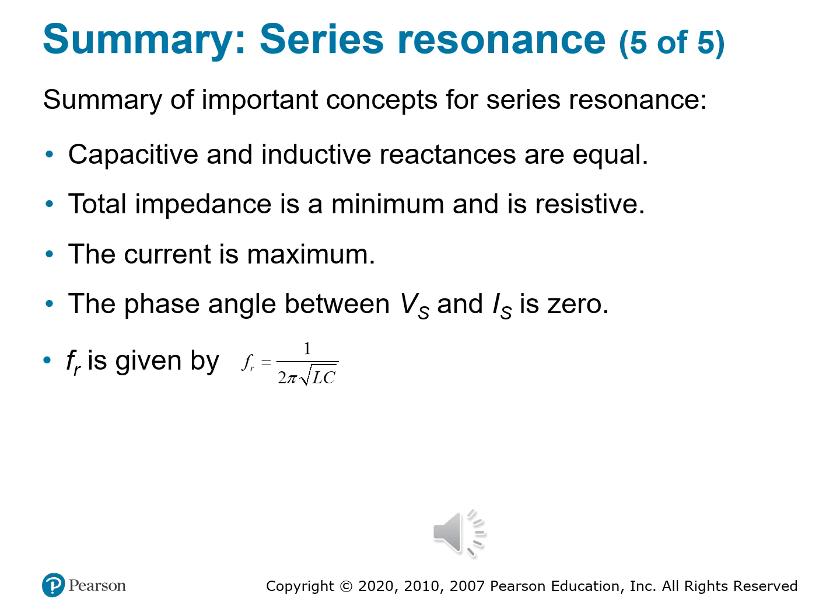And fifth, finally, your resonant frequency. The magic point is calculated using the formula f sub r, the resonant frequency, equals 1 divided by 2 times pi times the square root of LC. Let me give you a tip before we move on. That formula is your golden key to tuning circuits into radios, filters, and oscillators. When you design with resonance, you're not just solving a math problem, you're tuning your circuit like a symphony.